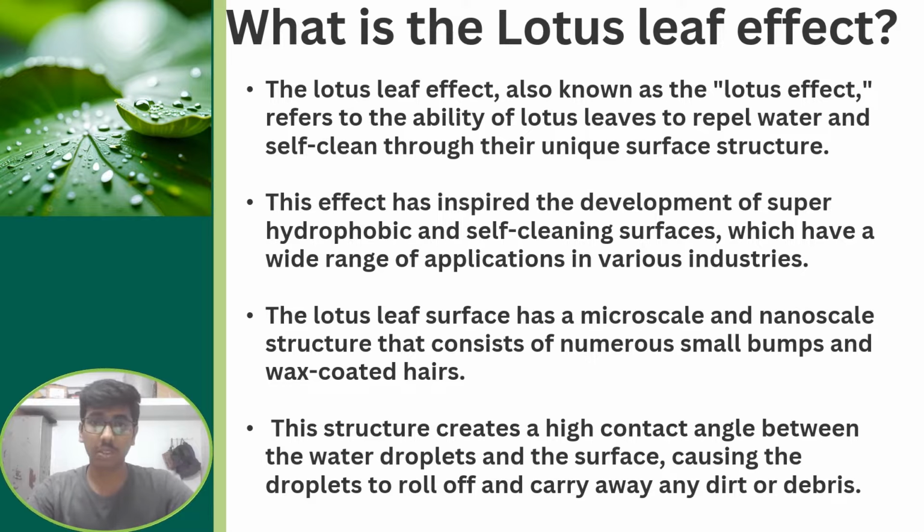The lotus leaf effect, also known as the lotus effect, refers to the ability of lotus leaves to repel water and self-clean through their unique surface structure. This effect has inspired the development of superhydrophobic and self-cleaning surfaces, which have a wide range of applications in various industries. The lotus leaf surface has microscale and nanoscale structures that consist of numerous small bumps and wax-coated hairs. This structure creates a high contact angle between the water droplets and the surface, causing the droplets to roll off and carry away the dirt and debris.